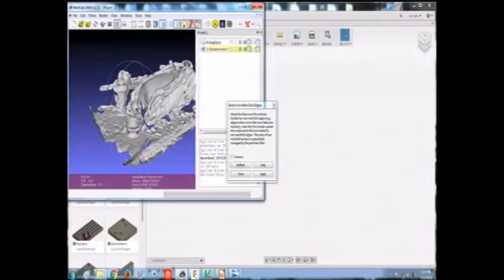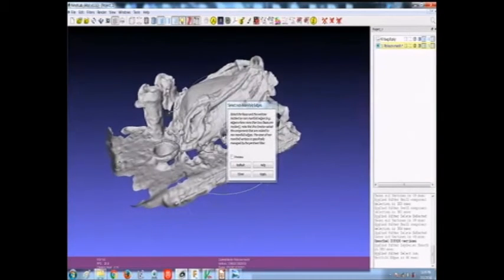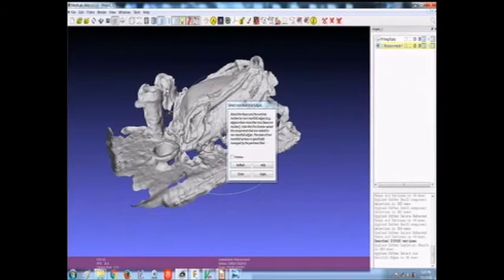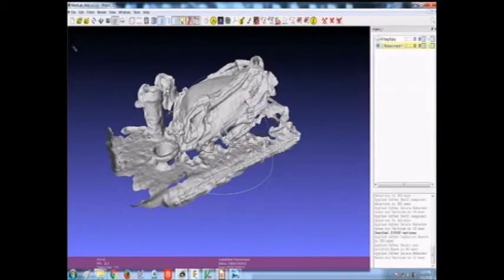I'm not sure if you can even see that red dot right here in the middle of the screen, but there's one tiny little vertex that was just sort of left over because of that processing algorithm, right? Like two little dangly edges that the software neglected to get that will screw something up later on down the line. This is important, otherwise I wouldn't be covering it, but just keep your mind tuned into that fact. So we hit apply, we got a few edges selected, bam, edges are gone.